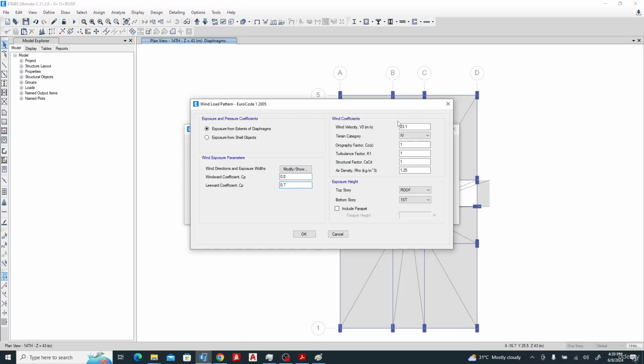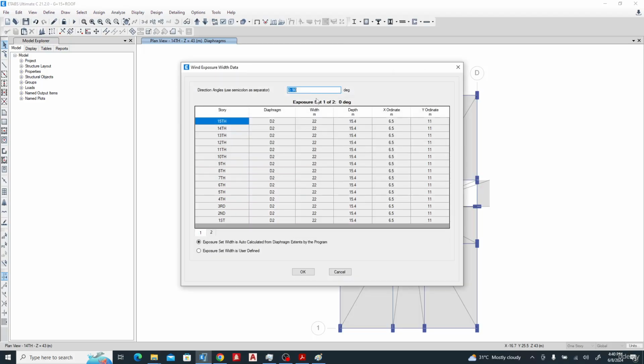Another thing you can do is you might decide not to use this method and just go there and use nodal load like I've been doing on Staad Pro. So whatever your wind pressure is, you just add these two together. So the total is 1.5, so you can just put 1.5 at this side, because the displacement from here will be the same as the displacement at D when it's going in this direction. So you can set all other parameters you want. So we have 0.8, 0.7. Now the thing we need to do is come to this here and change it to 0.